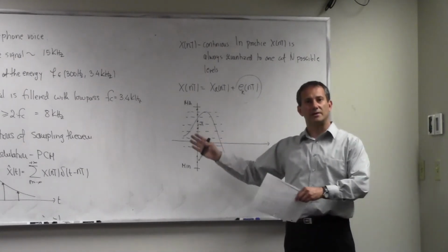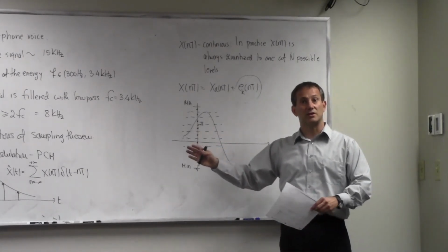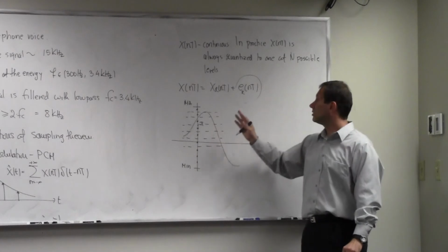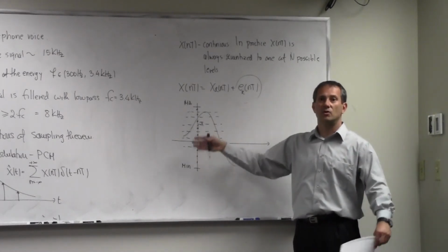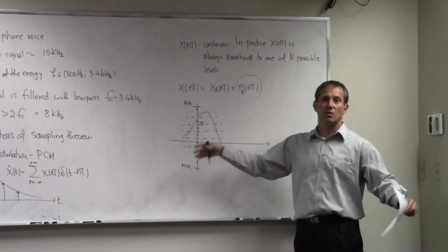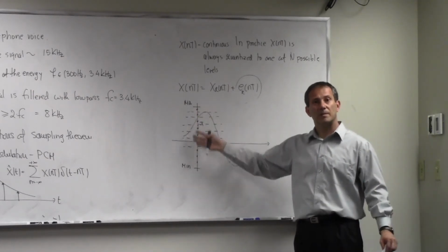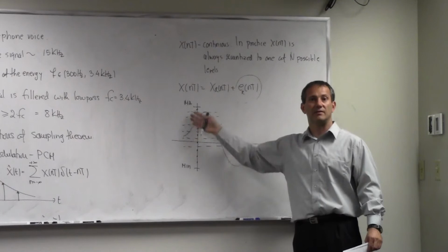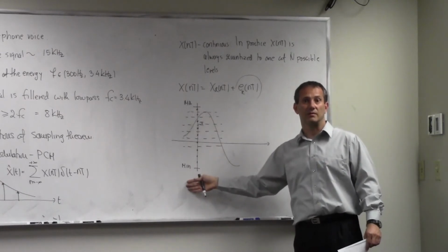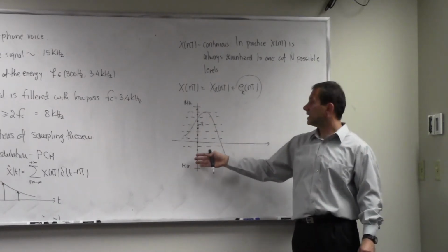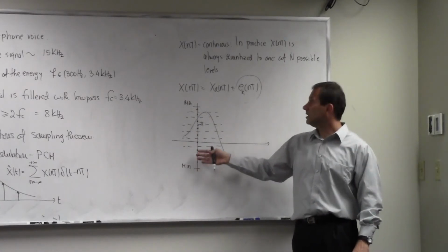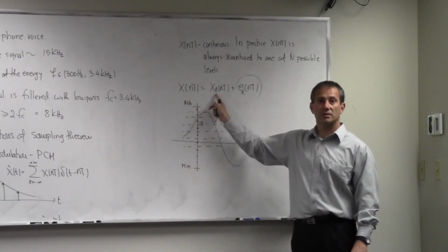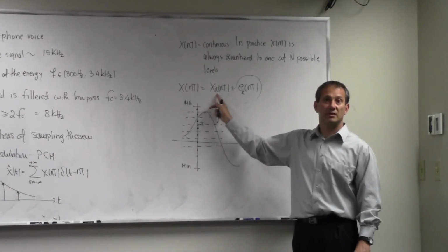Then, based on some math that I'm going to cover in digital communication, it tells you that in order to do this, you have to have 128 or 256 or 512 or whatever may be the number of discrete levels across this interval. And if I decide that I need 256 ranges, then that means every sample here I can represent with an 8-digit binary number.